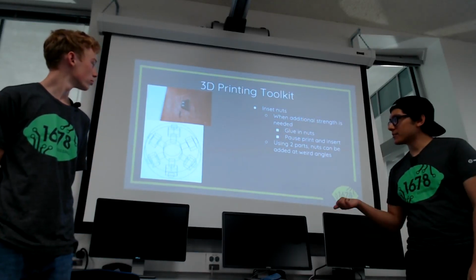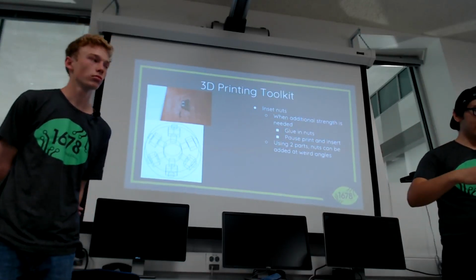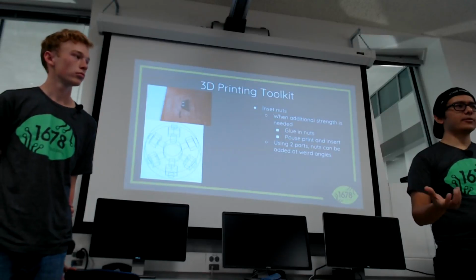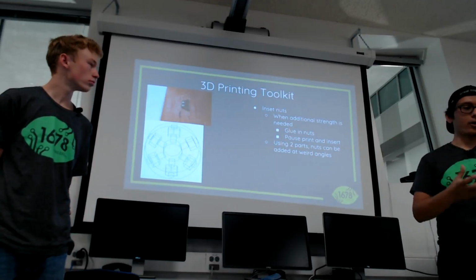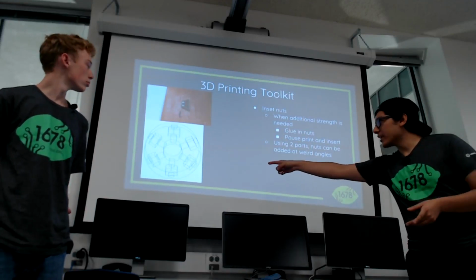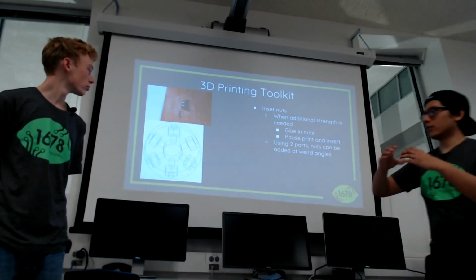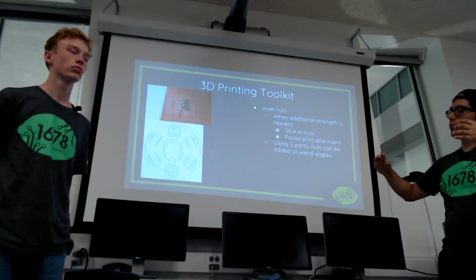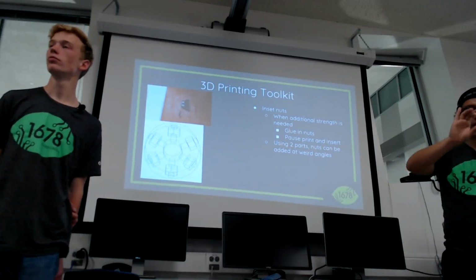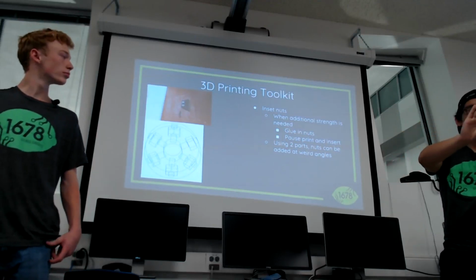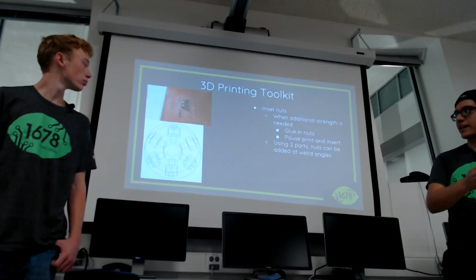There's a couple other types. So on our drum for our elevator this year, we used a piece of extruded tube, and then to power it, we actually made these plugs that were part plug, part pulley. And if you see right here, it's kind of hard to tell without rotating the model, but these are long slots that go along this direction into the board. And what we did was we just made the size of the nut as a rectangle and extruded through, and then the very end piece was the other half of the nut, so it's hexagonal.